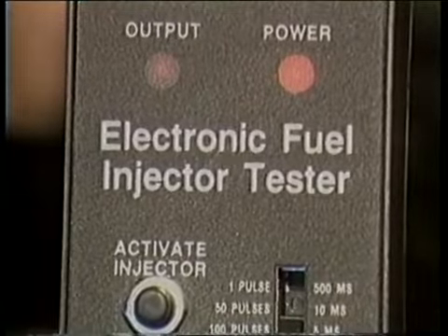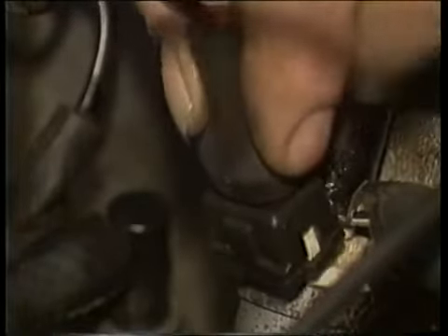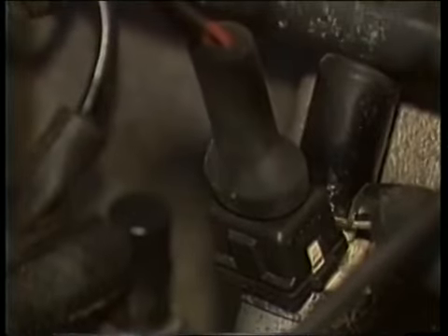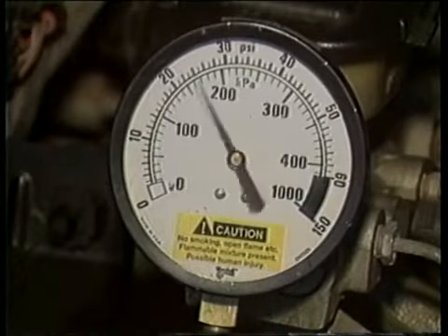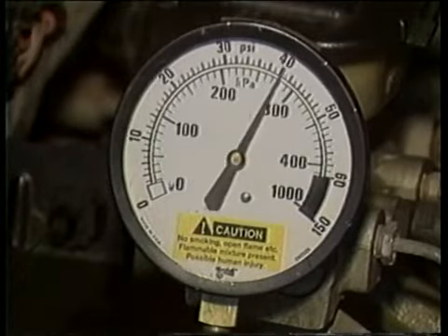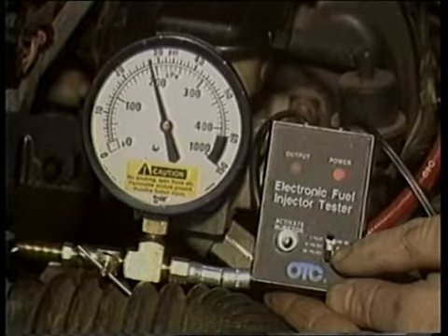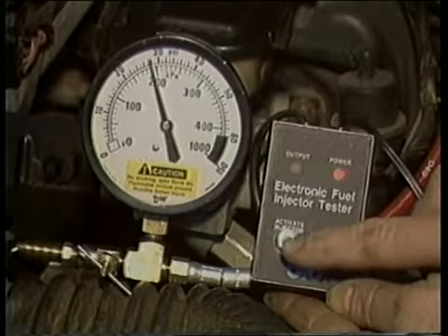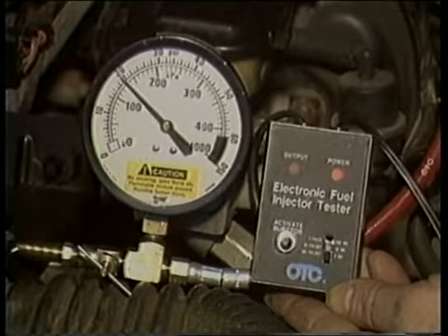This is another type of injector tester. Instead of measuring the actual flow out of each nozzle, it uses a pressure drop as a general method of performance testing the injectors. This type of test will give a general indication of injector condition. If pressure drop is less for one injector, that injector may be clogged and in need of cleaning or replacement. If the pressure drop is more for one injector, that injector may be hanging up and not closing quickly enough.